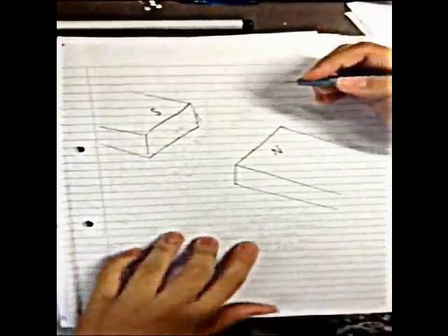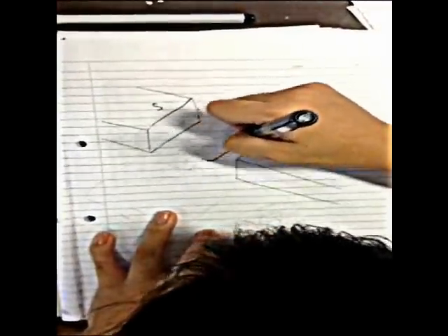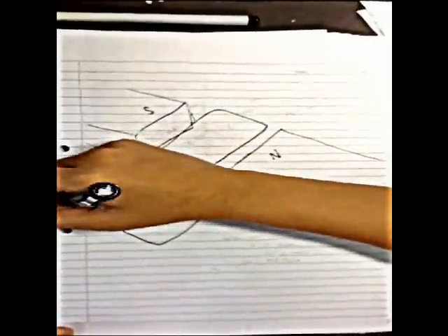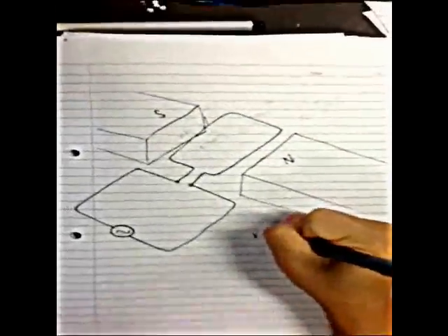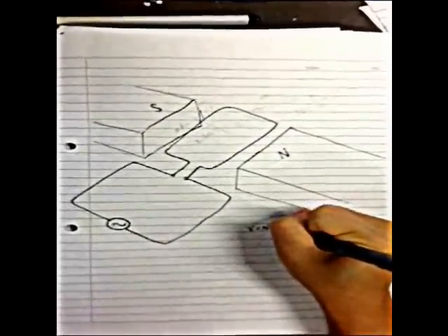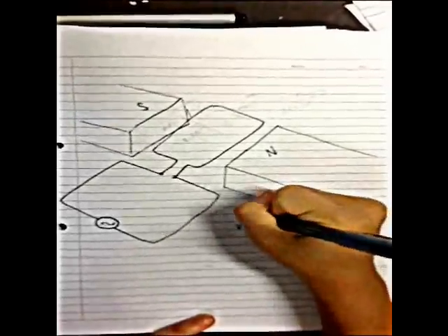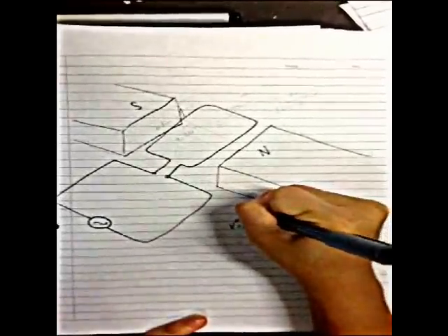Two magnets of opposite polarity are placed adjacent to a coil which will rotate to cause a change in magnetic flux linkage, which then will induce an EMF. The induced EMF is given by the formula NBAω sin ωt, or cos ωt.